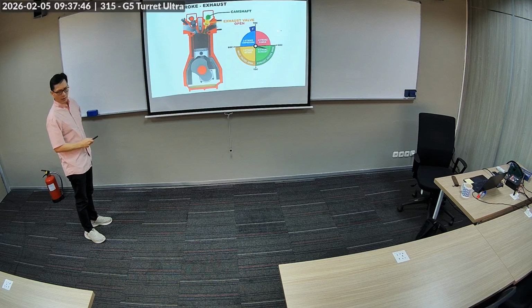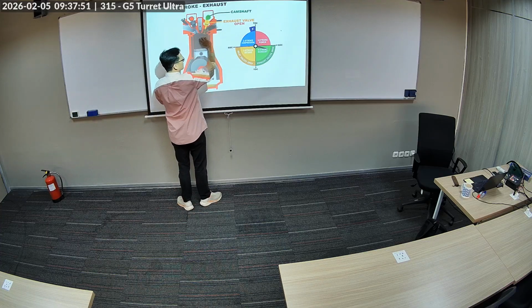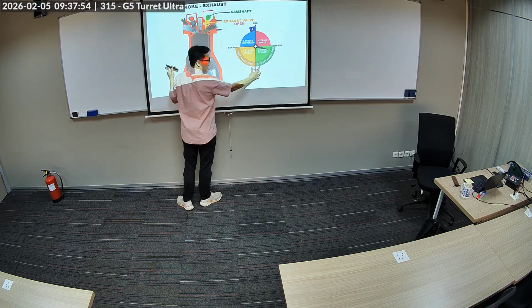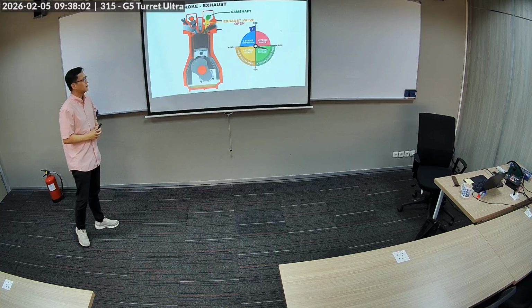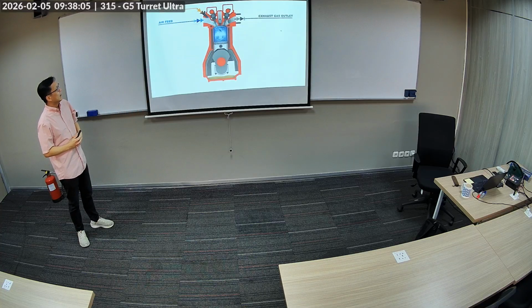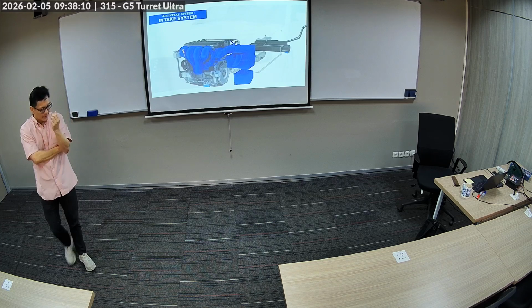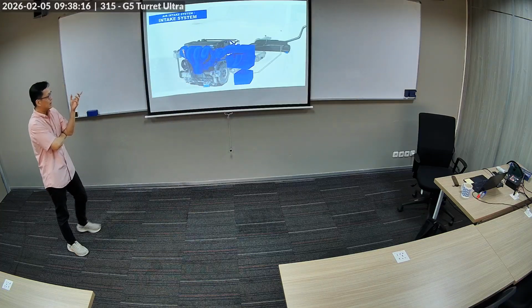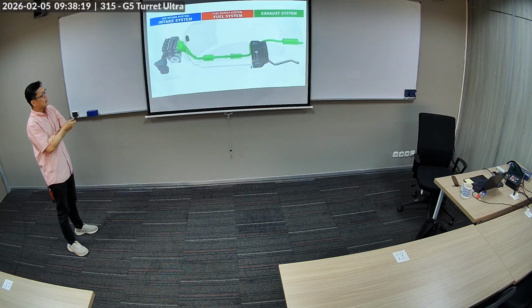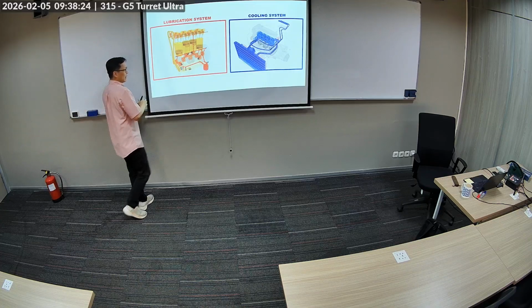Exhaust, we talk a little bit about the scavenging effect, right? So the speed at which this gets out is critical, and the exhaust valve opening and closing here does have some overlap, a little, maybe a few degrees, not much. Okay? So the intake will have sensors in it. It's called the airflow sensor. We'll talk about that. But you have the intake system, you have exhaust, you have the fuel supply, your lubrication systems.